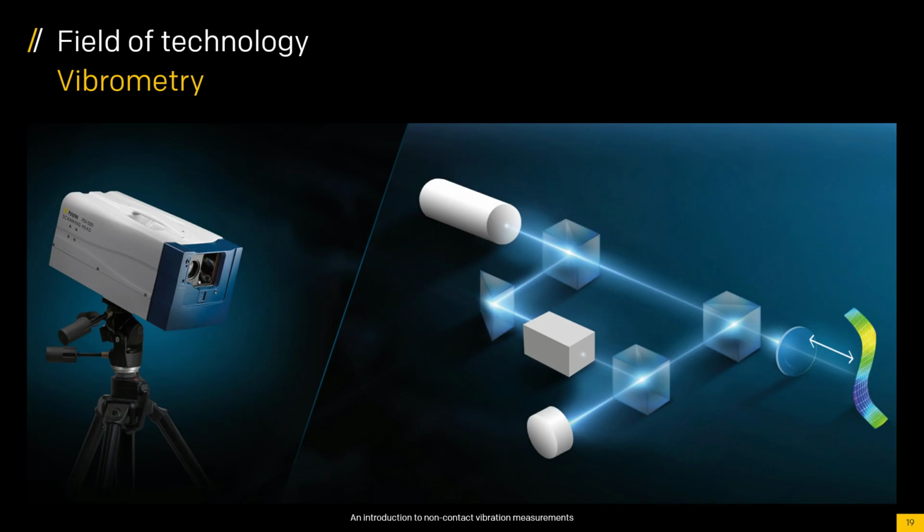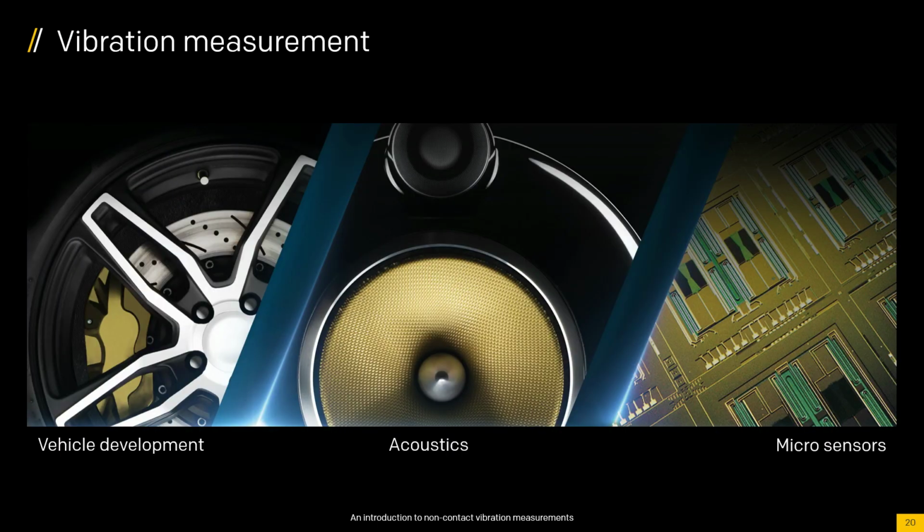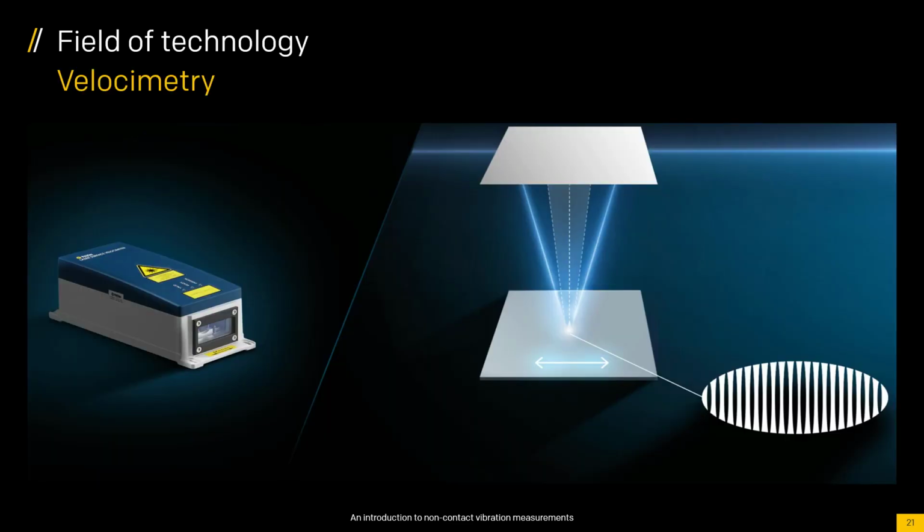Okay, perfect. Next question I have here: how is structural displacement characterized, which is excited with a frequency sweep, not a single frequency? What are the possible sources of errors in displacement measurements, and or calculation from velocity information in the sweep scenario?